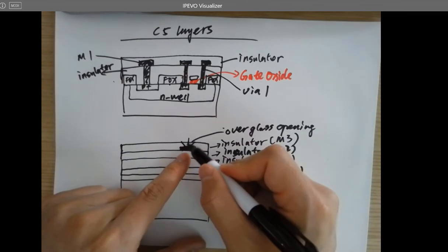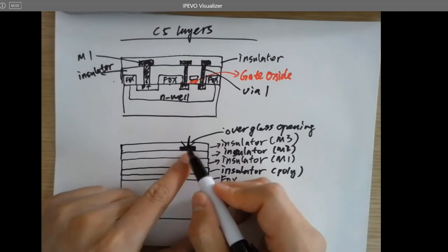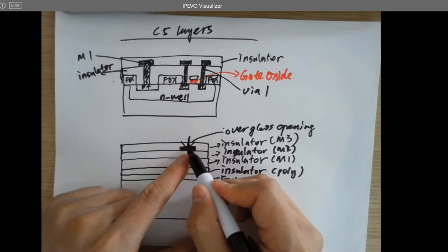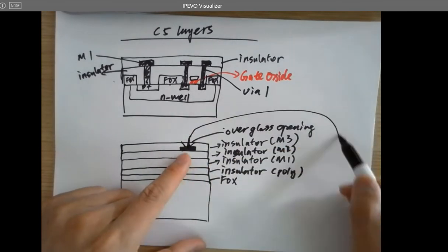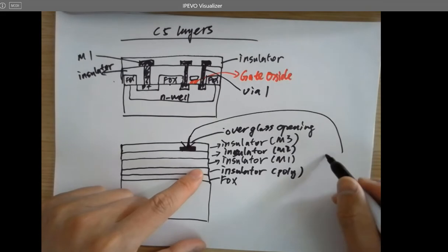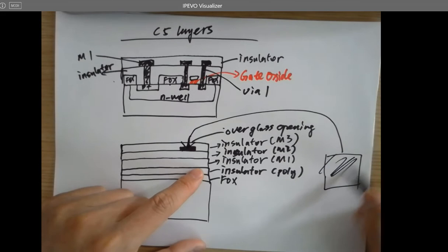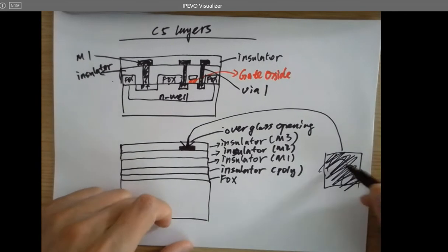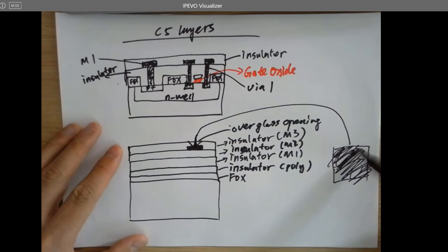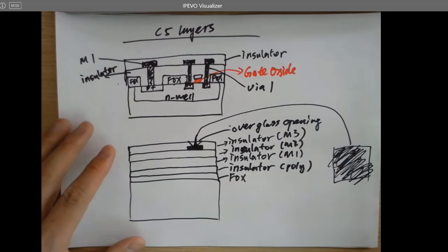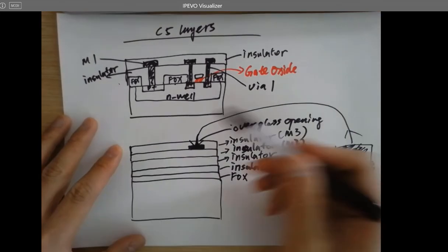So you can have a bonding wire, you can solder a very thin wire into the pad and connect this to the outside world. Normally it can be a way bigger pad, or the pin of the IC chip. So you can connect this to the probe to receive signals or inject signals into the chip, into the circuit, right?